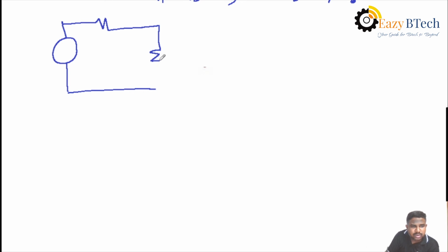Then find out the Millman circuit here. What is the Millman circuit? Millman's voltage in series with Millman's resistance. Then across the circuit, you rejoin the deleted element, 10 ohms. So this is Rm and this is Vm. Therefore, what is our aim here? To find the current passing through 10 ohms. That is taken as I10.